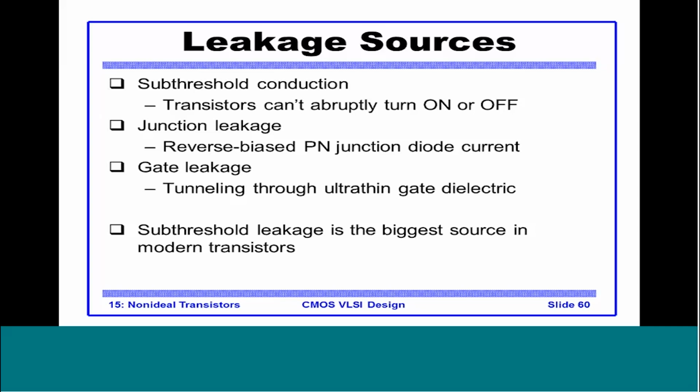And we also have to think about a transistor where, let's say, the gate is at VDD, or let's say the gate is at 0 voltage in a MOS transistor. We assume that it is off, it is not conducting current, but actually it is conducting a small amount of current. And let's say there are billions of transistors on the chip doing the same thing when the chip is off. So the billions of transistors will contribute a significant amount of current, and it is a very important factor now because a lot of these semiconductors are used for battery powered devices.